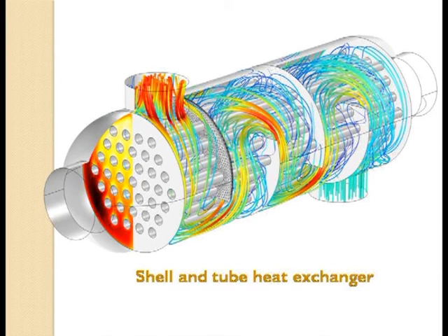Now as it comes here, it will find some kind of guide vanes or guide supports. Half of it is covered, not fully, so the fluid will be guided to move in this direction, then it will go from the bottom of this guide vane, then go up, then again be circulated like this, and come down again, like a passage formed. Now you see there is another baffle here. This baffle will make the fluid go from this direction to this direction, because the baffle will stop it. Then again on top of the baffle it will come in this direction, and there is another baffle, it will go from the bottom of that baffle, and like that the flow is made to move around and around and around with good turbulence.